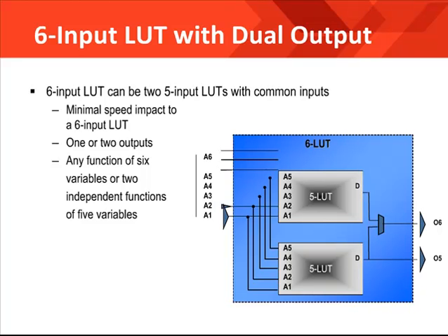Also keep in mind that if you're trying to design at the maximum speed quoted in the device datasheet, you have to remember to limit all of your delay paths to 1 LUT or 1 logic level. This is not typical, but some customers do it by extensively using pipelining and by minimizing their combinatorial logic. The Designing for Performance course discusses pipelining.